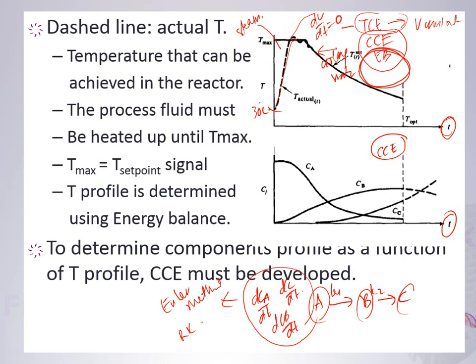Okay, so when that happens and you plot this out, you will know the profile of CA, CB and CC. You can imagine this, right? Because remember, in your energy balance, in your EB, there's an expression for K there. Remember? It's minus lambda V K CA, and then especially when you have this, you have to take care of A, B and C, K1 and K2 and so on. You remember that, right? You can imagine that.